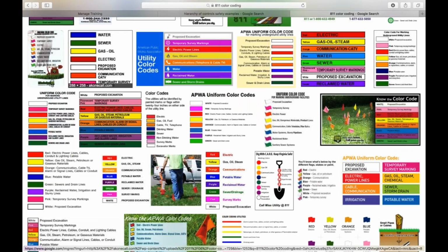And then, of course, field office storage, lay down areas, where we're going to have these areas put, right? We're going to make sure we designate the areas, make sure that they're accessible by truck, forklift, or crane, depending on what we're going to be using at the time. Don't have them too congested, in order for them to be able to safely handle the material and operate and maneuver through there. Any restricted or congested road areas, let's describe it as well. It may be a road that may be kind of tight, where we may have to make it one flow of direction of traffic, right? Or one direction at a time traffic, possibly.